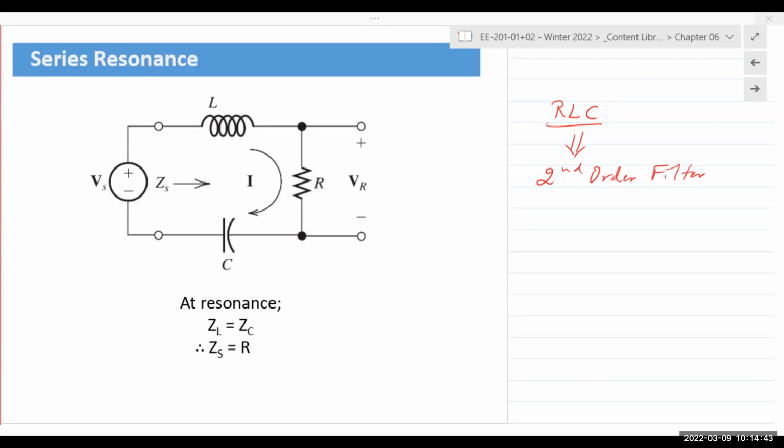the capacitor. So let's say the inductor and the capacitor are charged up to a certain level, right? Now, you combine the stored energy along with the energy that is provided by the source. Vs plus VL or plus Vc could end up being much larger than anything Vs is providing. One of the reasons for that is because capacitors and inductors are duals of each other. So the energy is constantly flowing in and out of the inductor and the capacitor, right?